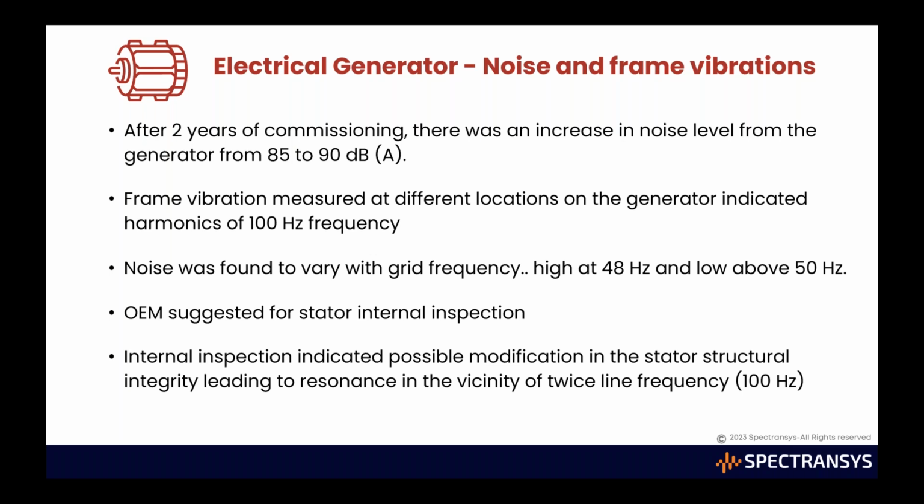Then the frame vibrations on the generator's frame, not on the bearings, on the generator frame, the structural framework, data was collected. Frankly, it is not normal practice. But somebody advised that because the noise is coming from the generator frame, from within the generator, let's make a vibration survey on the frame itself.